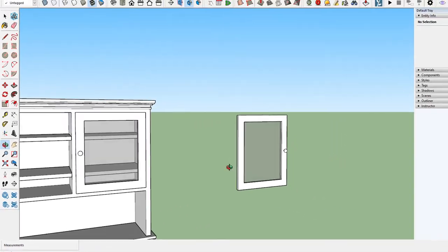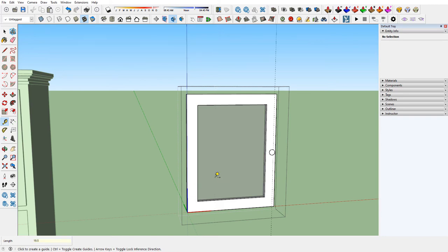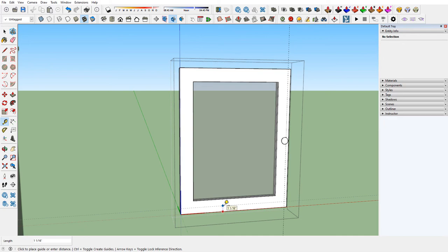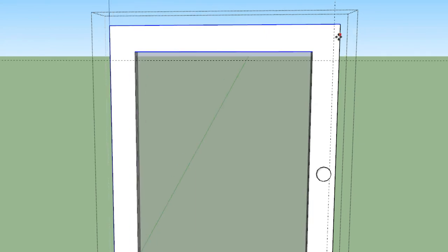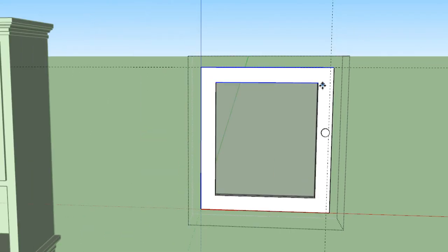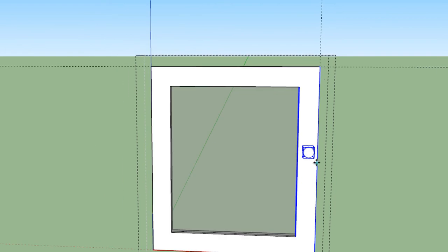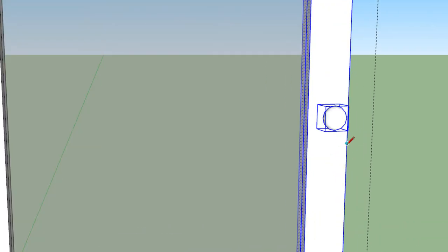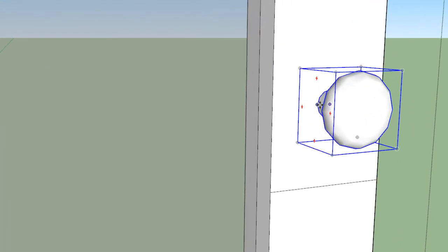It's the right size. This other one, the same thing, we just go the other way around. We'll go tape measure tool, click, come across the surface in the red, 19.5. And then here, go up, 22, and it's just the same thing again. We would just go ahead and select and go M for move, click here and go down in the blue, select M for move here and come across in the red, draw a line, select the knob, M for move, click and come down.